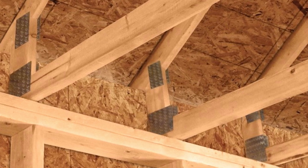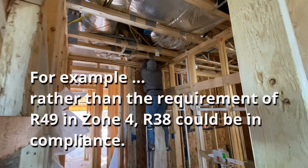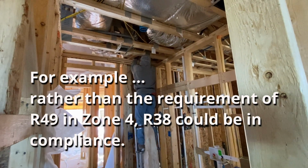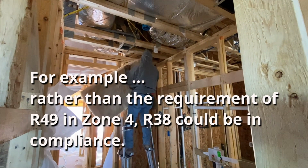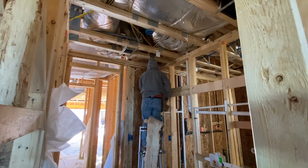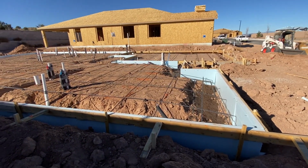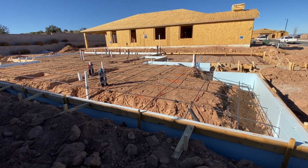An exception in R402.2 of the code lowers overall required R value in ceilings for using raised heel trusses. This allows installing continuous insulation over the outside top plate, and that saves a significant amount of energy. This means rather than being required to have R49 in Zone 4, for instance, you could be in compliance with R38. Talk with your truss provider about this option. This may be a cost-effective way for you to build a better home and reduce your installation costs.